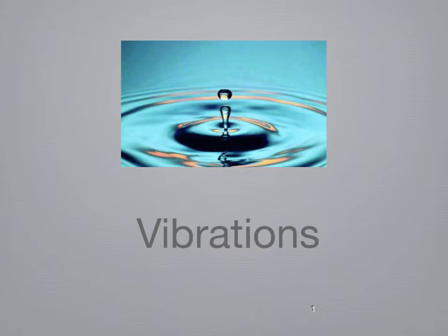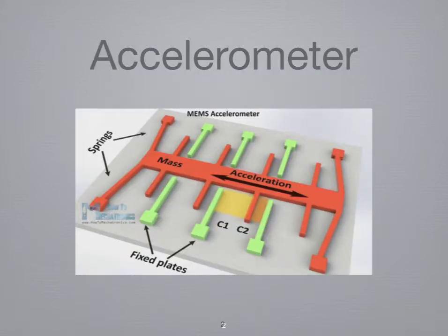This lecture is on vibrations. It's apparent that the intensity of vibration can be measured either in terms of displacement, velocity, or acceleration. Acceleration is clearly the best parameter to measure at high frequencies. However, because displacements are large at low frequencies, it would seem that measuring either displacement or velocity would be best at low frequencies. The amplitude of vibrations can be measured by various forms of displacement transducers.